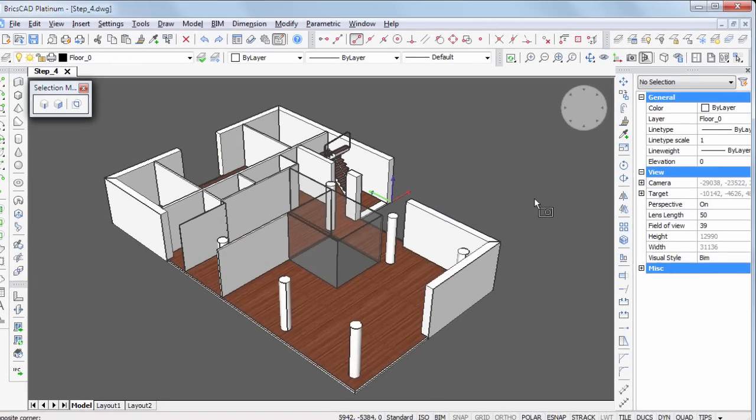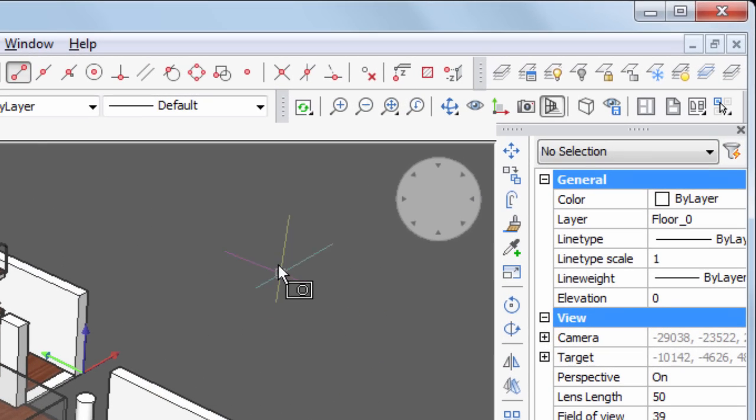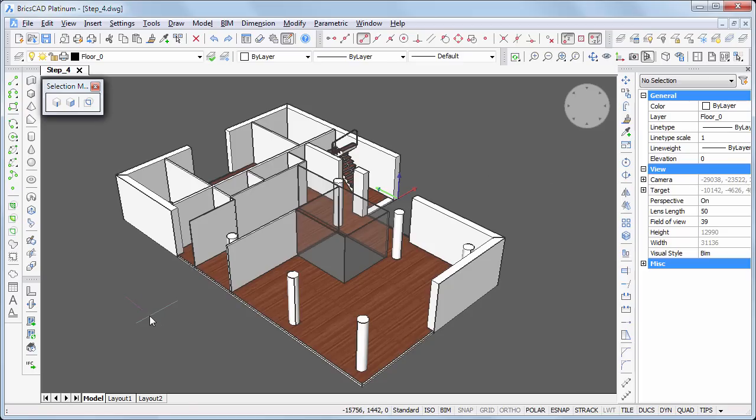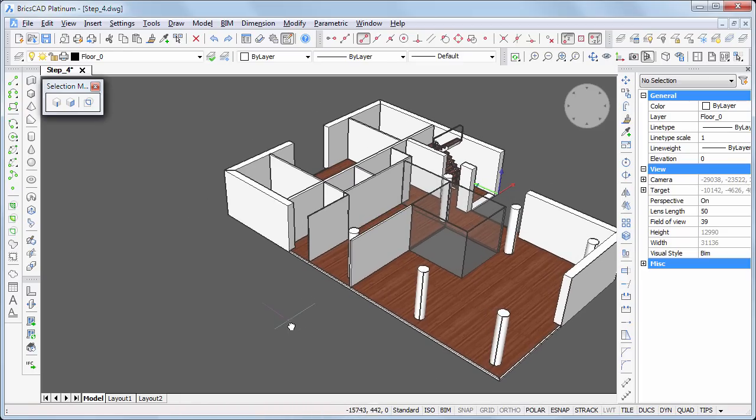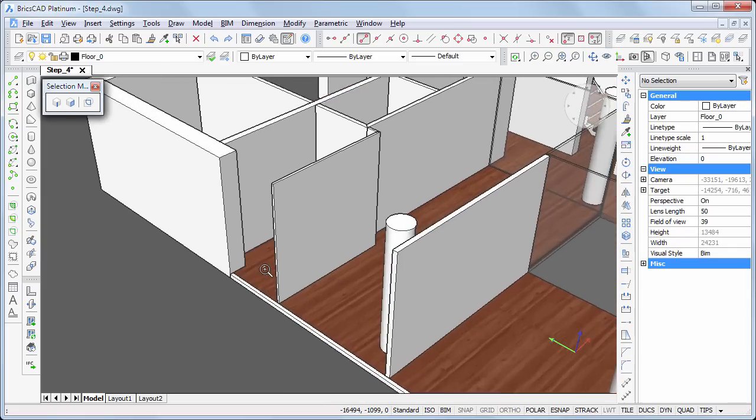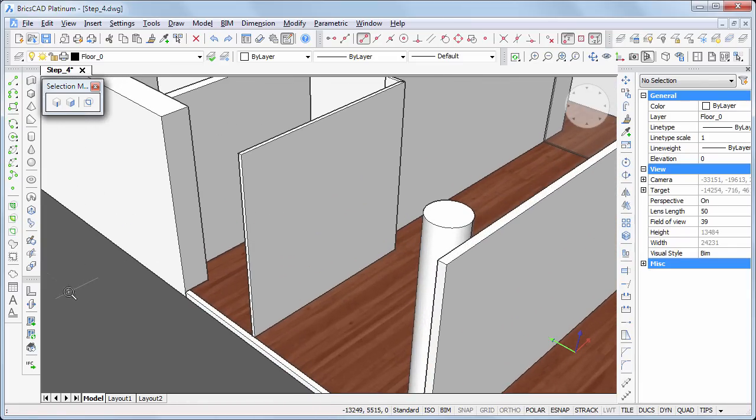To force entity snap points to lie in the XY plane of the dynamic UCS, switch on the Ignore Entity Snap Elevation option. Also allow entity snaps to negative Z values. These settings assure that the origin point of the windows and doors lies in the face of the solid.